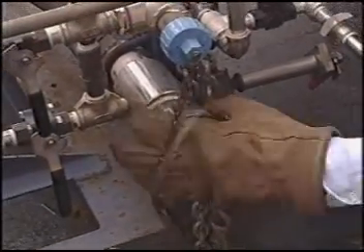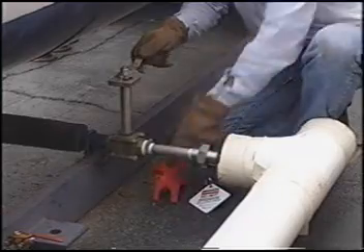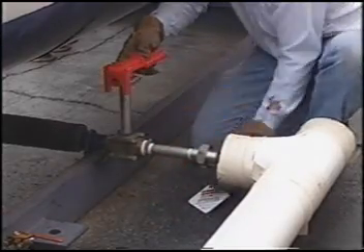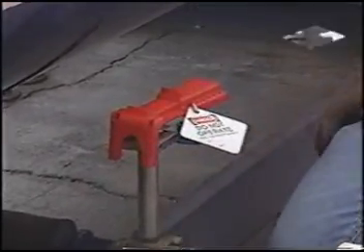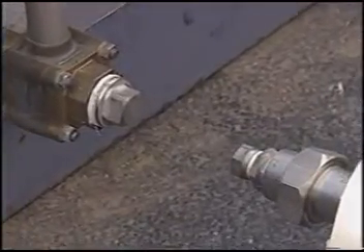Avoid danger by closing valves and disconnecting all of the vessel's lines. Just shutting off a valve may not protect against asphyxiation in a confined space. Valves leak, and they can be opened accidentally. To be sure, isolate any confined space connected to any gas source other than air.